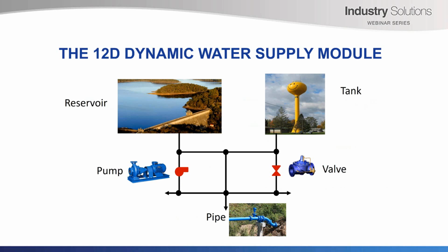You could also use the software to optimise your network. So you could optimise water sources where you've got multiple tanks. You could optimise pumping schedules to account for demands and energy costs. You could develop a pipe cleaning or component replacement strategy for your network. You could also develop real-time management strategies with embedded rules and controls in the software. So this is when you want to get into the complex stuff, but today we're going to focus on the fairly simple subdivision type of water reticulation design.